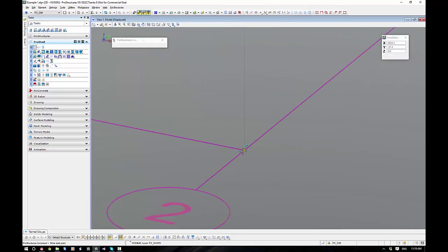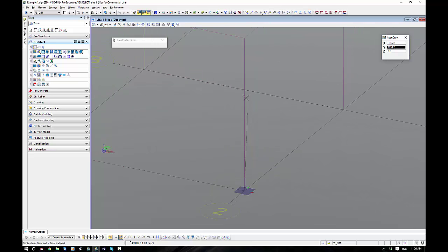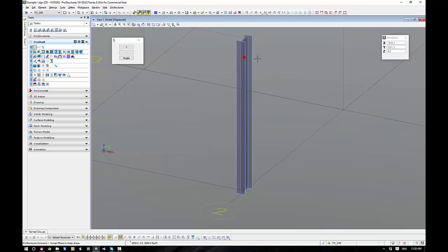So 2 point, and we're going to practice some of our funky snap tips. I could snap it to the corner there, but I get really worried that it's going to pick the wrong thing if I've got lines over lines over lines. So what I want to do is come away, hover over the line of the grid, and you can see that I've got an implied snap there. Left and right mouse button together, I have my tentative snap, accept. Up the top, you don't want that one. You want the implied snap, so pull it back a little bit. So we get the implied snap, tentative, left and right together, accept. You want to get good at that, which is why I went through it.